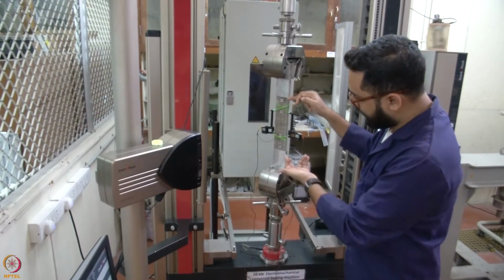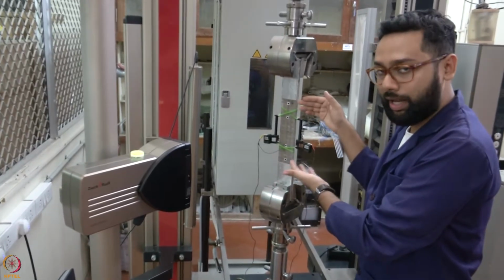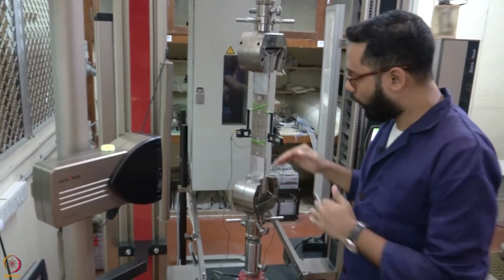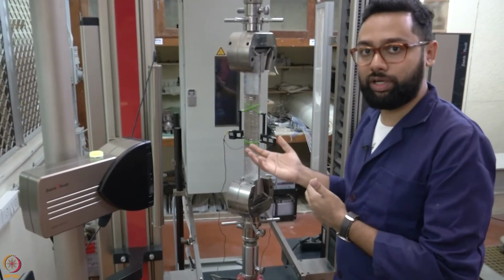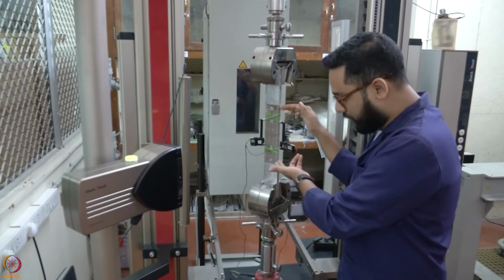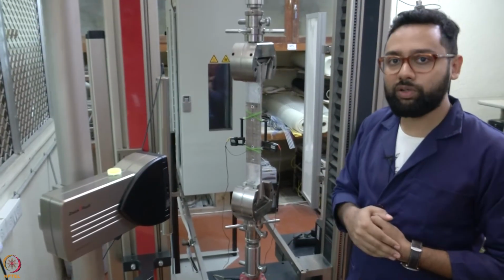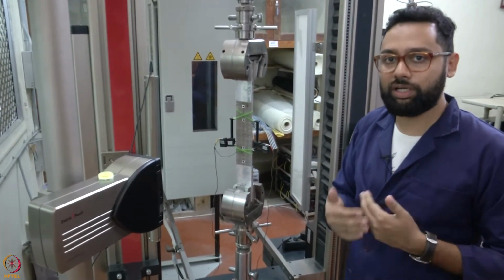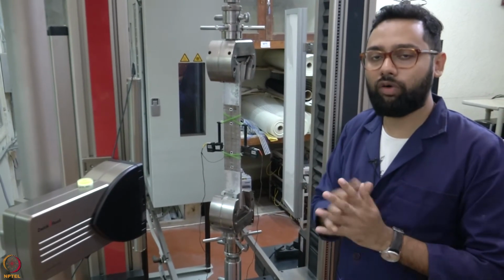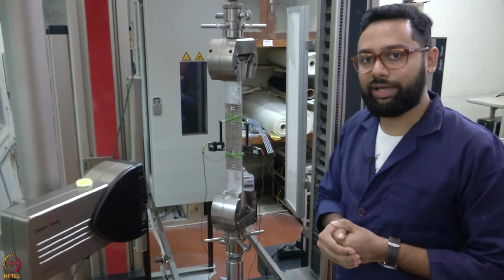So, the video extensometer can detect between any given 4 points or 5 points or any n number of points given in the framework of the video. Once we have tested, for example, if you need to find the displacement over a gauge length of 200 mm, you can test between that gauge length, and then after testing you can go back to the video and find the displacement between any other gauge lengths provided in the frame of the video. So, that is one of the advantages of a non-contact type extensometer.